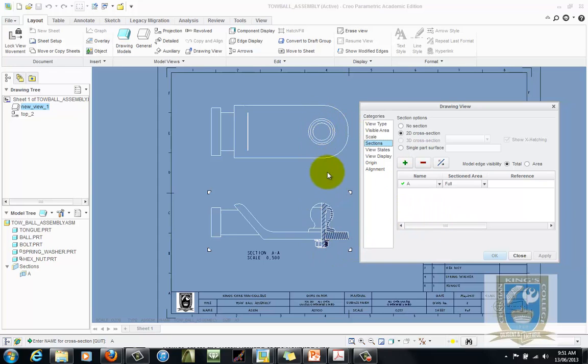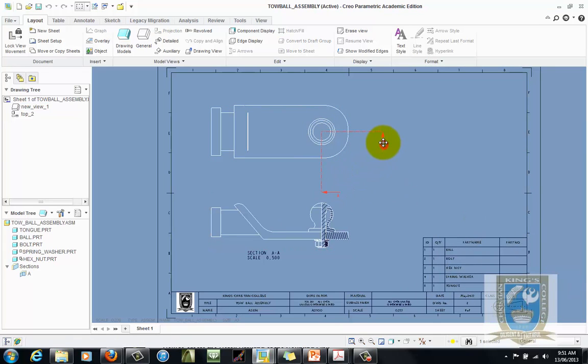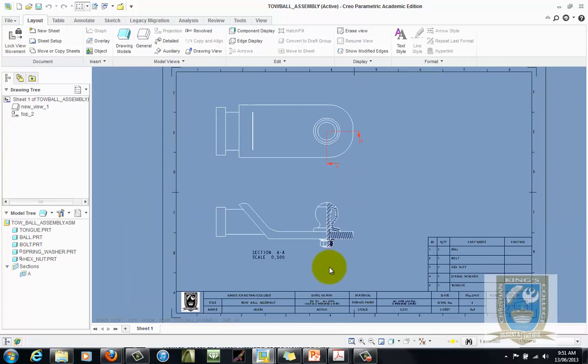To include the two lines that represent the sectioning cutting planes, scroll along here, click on the arrow display box, select the top view, click apply, and we can now see that we have our two section lines to represent the half section. Click Close. I'll probably do a little bit of tidying up here, move my arrows in, and then do your usual thing about conventions with sectioning.